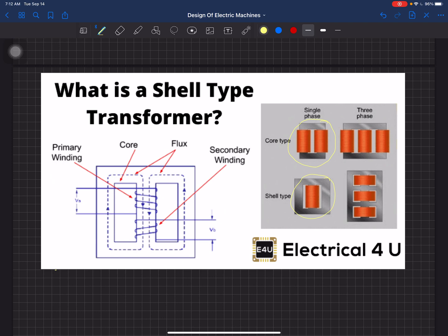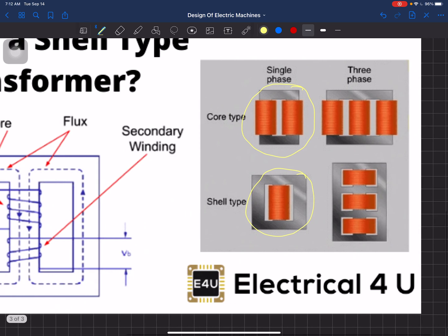So this means that if I zoom in a little on this one, I have this first one, the first N1 winding, and the second winding is going to be just below that. Or maybe they are going to be done above each other, which means the whole yellow winding covers the whole limb, and then the red winding is done on that one. So these are the first phase. This is phase A, this is phase B, this is phase C.